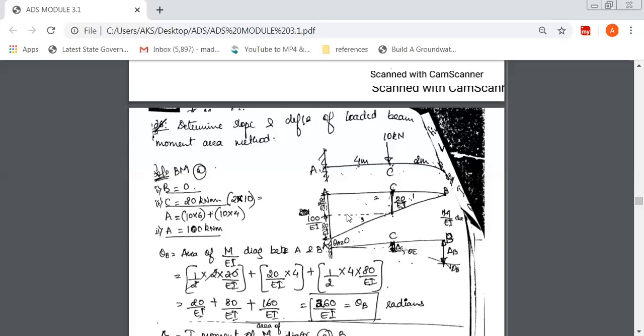Now what we'll do here is to make things simple. This is 20 and this is 100. You can treat this as a trapezoid also, but remembering the area or the CG of a trapezoid is a little complicated, even the simplification. So to make things simple, this is 100, this is 20. So I'll just draw the straight line here.